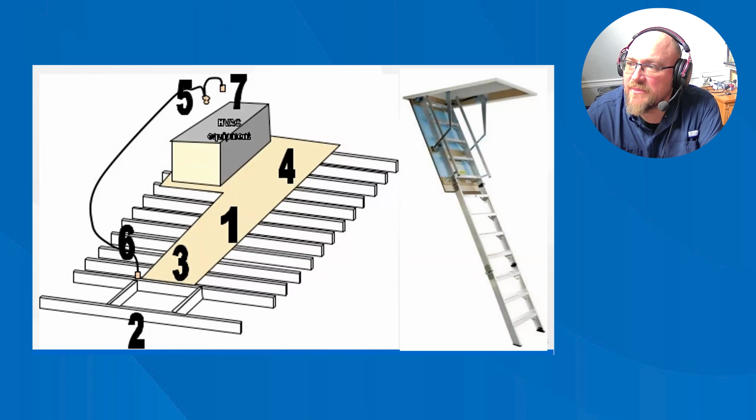Some of the more common defective conditions observed by inspectors include: cut bottom cord of the structural truss. Often homeowners will cut through a structural member in the field while installing a pull-down ladder, unknowingly weakening the structure. Structural members should not be modified in the field without an engineer's approval.